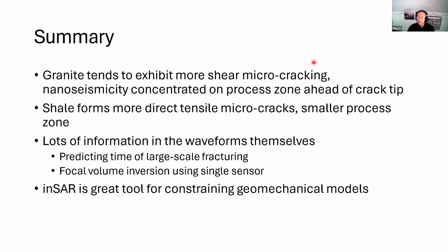Yeah, absolutely. So you said this was the GAP test? GAP, yeah, that was published in PNAS, Proceedings of the National Academy of Sciences, 2020. It's an absolutely simple device where you take a 3-point bend specimen with a notch in the center, and you put the end supports with a gap. The initial loading is introduced by putting elastoplastic pads next to the notch.